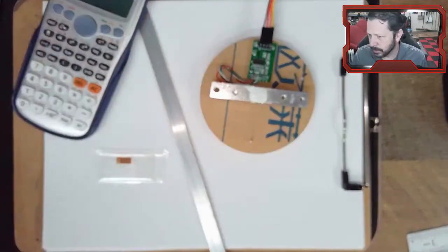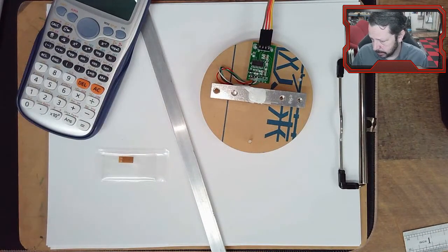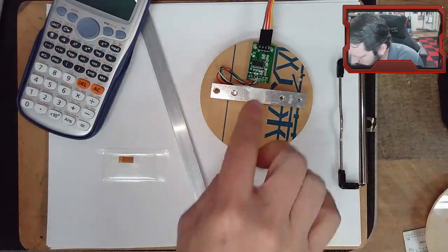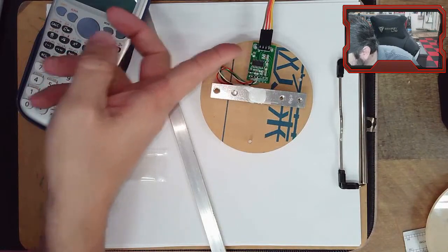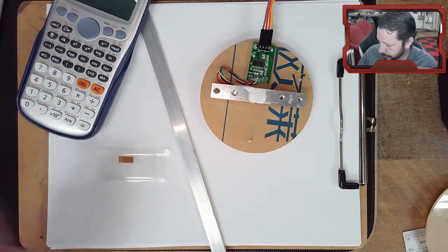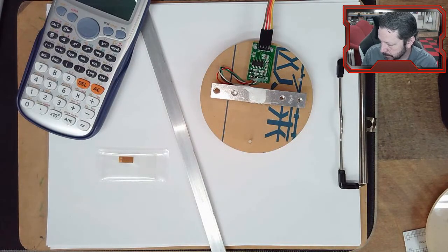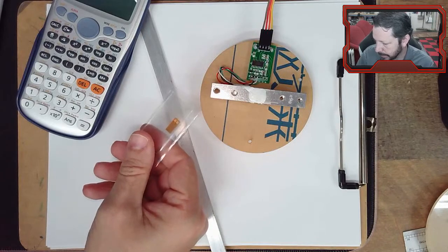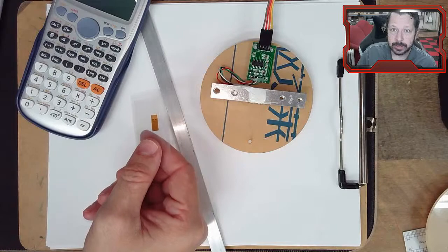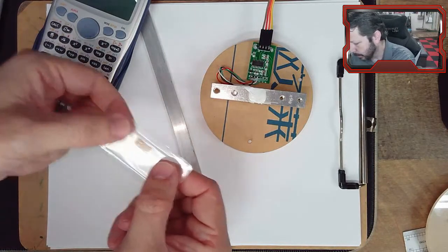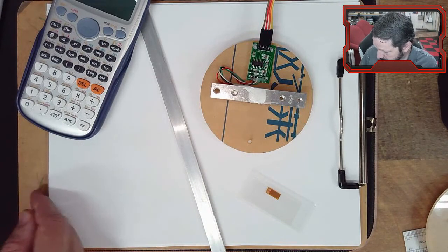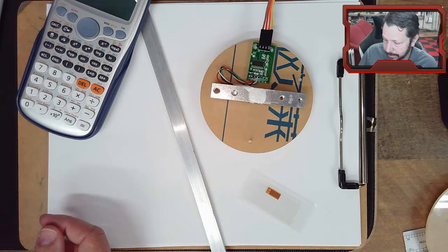Right now these wires are going over to the Arduino, and it's got some code running on it to measure this strain gauge. This little chip right here is an HX711. It's a particular chip that helps with measuring the strain gauge. The way these work, we'll talk about these later, but they again change their resistance. But this time they change the resistance with strain. So as they strain, either they get longer or shorter if the beam is in tension or compression, and they will change their resistance, and we can pick that up.